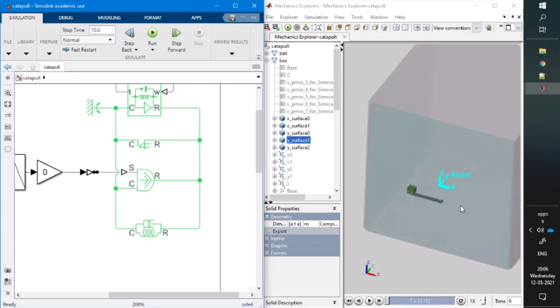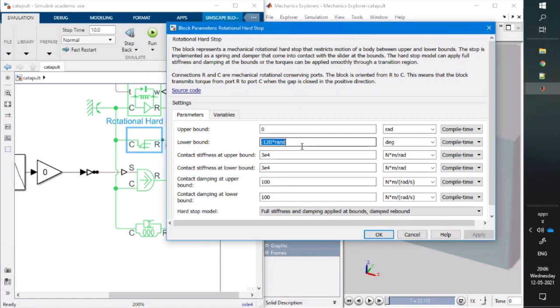It has been constrained because this vertical is its limit and it has been stretched here. Whenever it hits, it should bounce off that vertical limit. So I have a hard stop here. I say that my bound, again, is a random number because I want to have multiple variations. I'm giving stiffness and damping when it hits that limit.